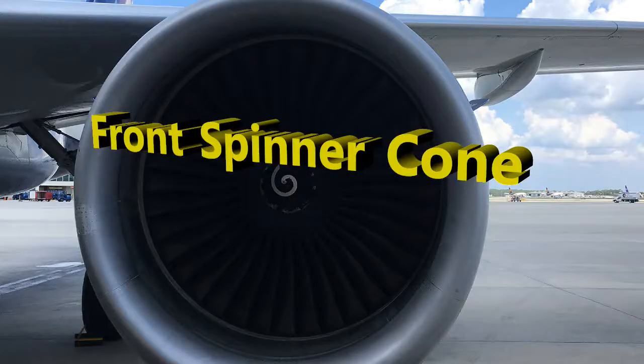Okay. Now, remember I said that you have the front spinner cone, and it is attached to the rear spinner cone by a rear flange, and that connection is important. There are 6 places where it's connected and screws in. So just be aware of those details. And again, follow the instructions from the maintenance manual as far as installation, because you don't want to be careless with all of that. Pay attention to any indent marks there for proper fitting of the screws, etc.